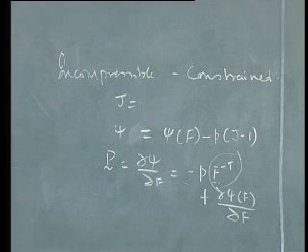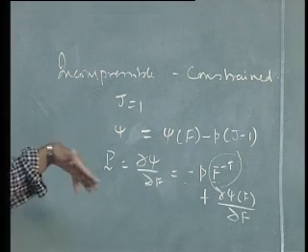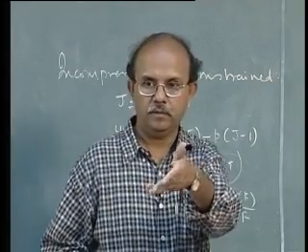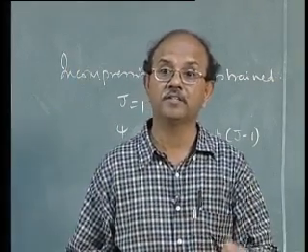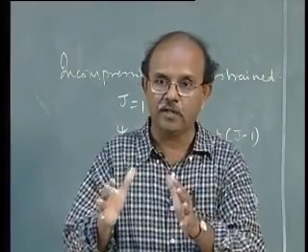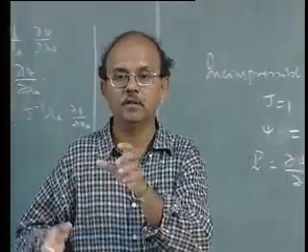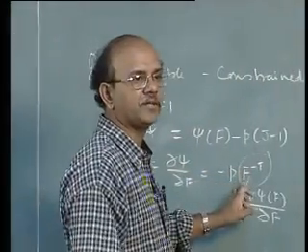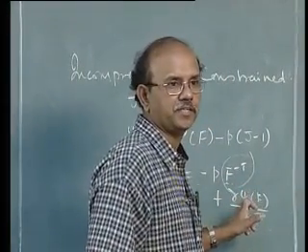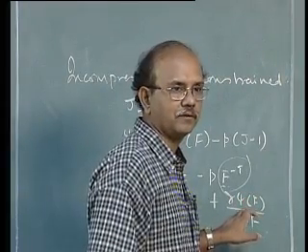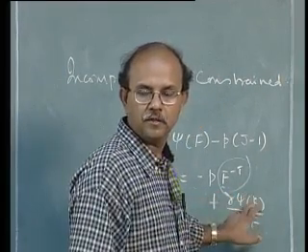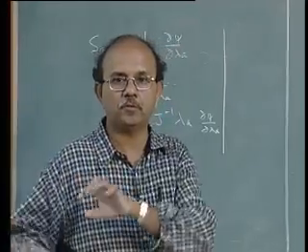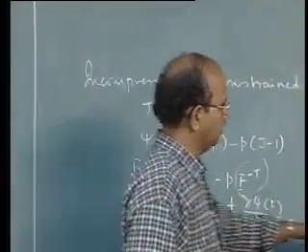Determinant of A, that is dou J by dou F is equal to determinant of J into F inverse transpose. The determinant of J became 1. So that's the doubt. Why I left out J is because J became 1, because that is the incompressibility condition. That is why J is not here. So that's why I write straight away minus P F inverse transpose. So determinant of J into F inverse transpose, determinant of J became 1, and that's it.